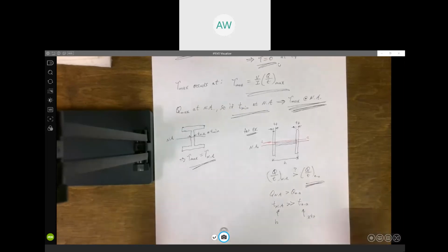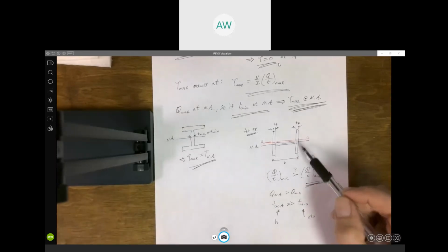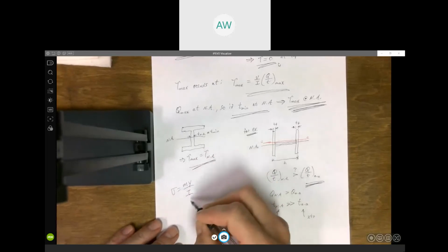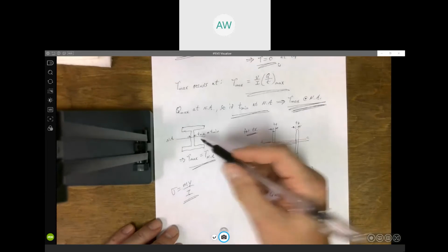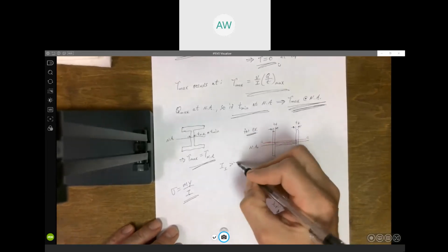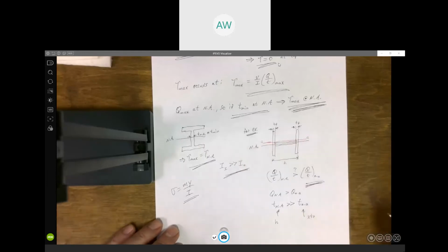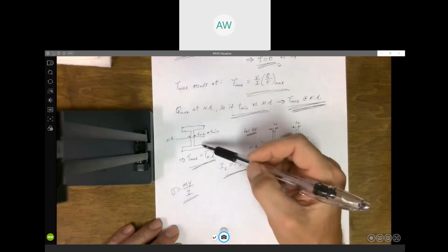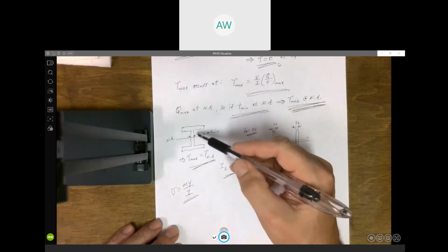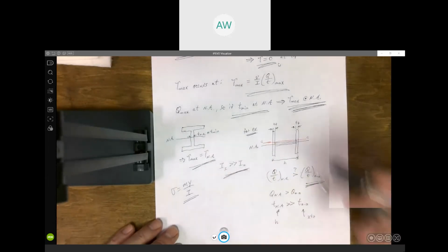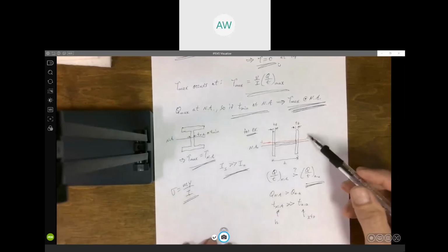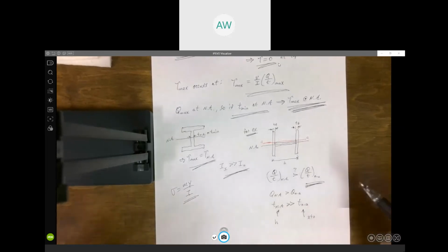Now, again, this is not going to happen very often. You don't see I-beams turned like this for a reason. The moment of inertia is a lot less. You've got a weaker beam. Sigma is equal to My over I. So the larger the I, the lower the stress. Well, I for the I-beam is much, much greater than it is for an H-beam. So that's why you don't see I-beams turned this way. It's a stronger beam. That's the whole purpose in an I-beam having a cross-section like this. You increase the moment of inertia by moving the area away from the axis. That's the motivation for having an I-shaped beam. But, for some special circumstance, you could run into a beam like this. But not very often, right?